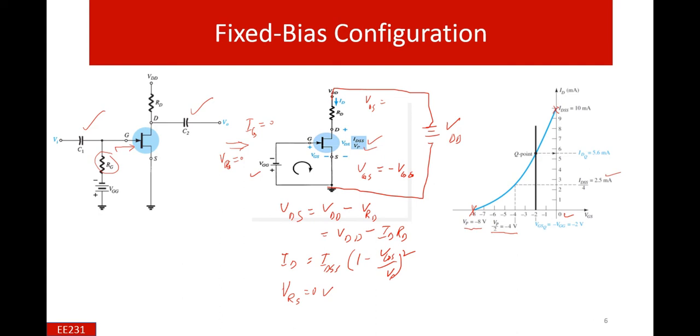And definitely if the voltage is given as -2, then we can find the corresponding current at the Q point, which is this one. Q is the operating point, which lies on this blue line. So if we select some Q point here, we can change this point accordingly if we change the voltage VGS. Then drawing the vertical line as well as the horizontal line, this is the current corresponding to this Q point, and similarly if we draw the vertical line here, this is the VGS value. And definitely these points can be found through graphical methods.